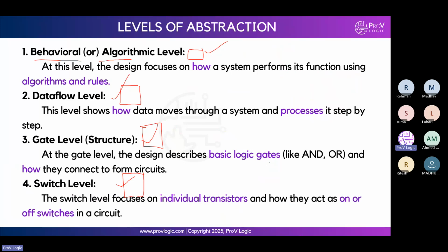Okay, in Verilog we have 4 levels of Verilog programs. Of these 4, which is mostly considered in industry practically to design projects, first priority is behavioral modeling, second priority is data flow modeling. Gate level we can use, but as a third priority. First is behavioral, because in behavioral we can design any functionality easily.